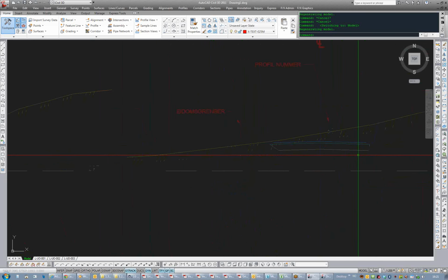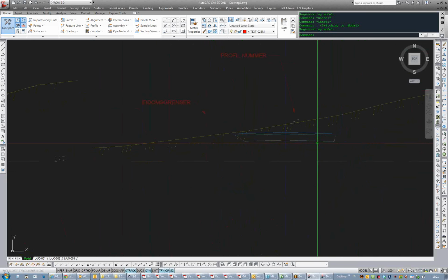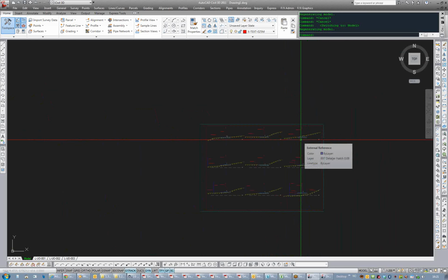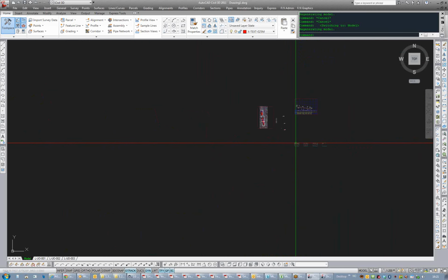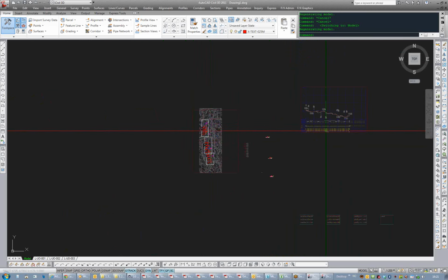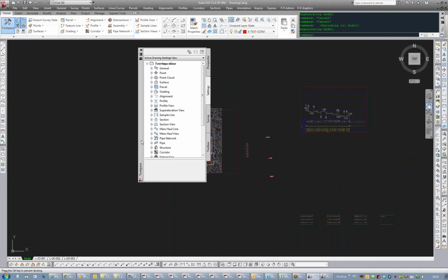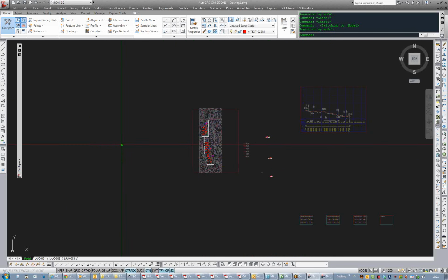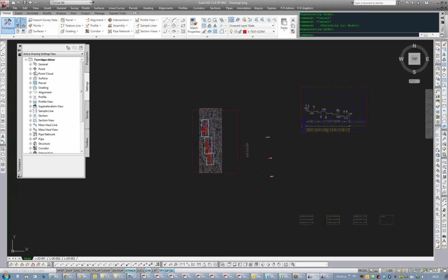Well, it depends on if NovaPoint allows you to edit your section views. In Civil 3D, you got your prospector out there somewhere? Ta-da. All right. Go down to section view. Go to prospector tab, not settings. Sorry.